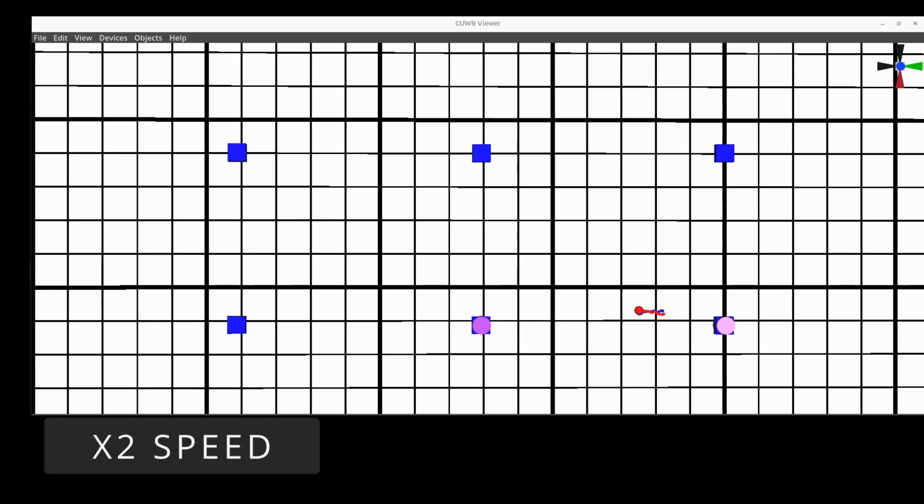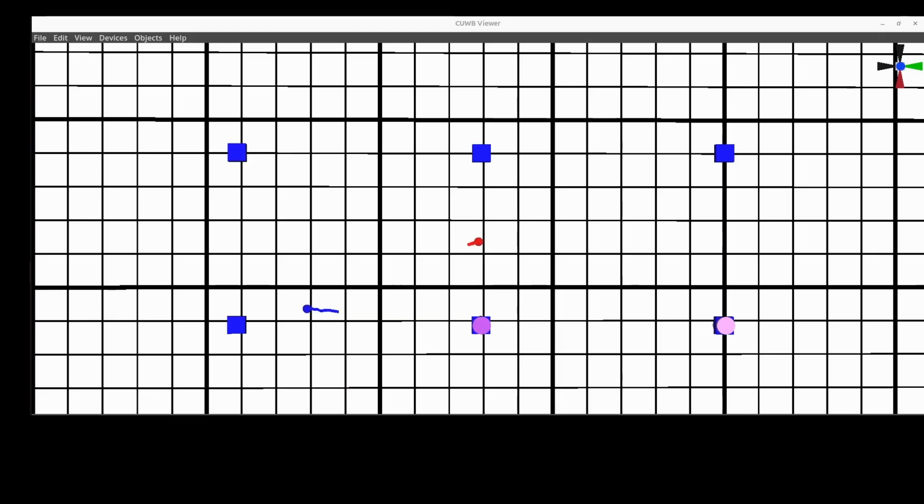As we play back the data, tags initially start tracking fairly close together. The error tag snaps to the average position of the anchors that heard the tag. This is due to the calculation of the tracking being flagged as poor and shifting to low anchor count tracking or imprecise tracking. The tag continues to snap periodically to the correct tracking path, but then returns to imprecise tracking.